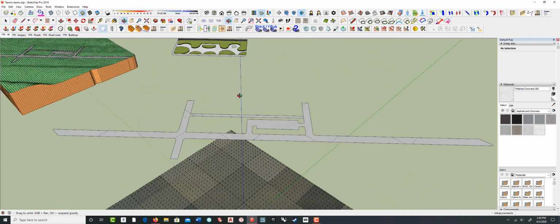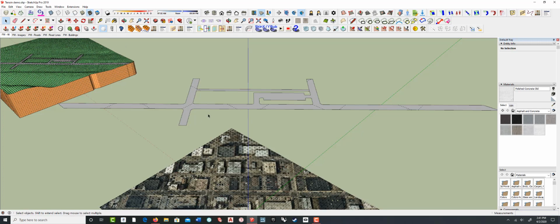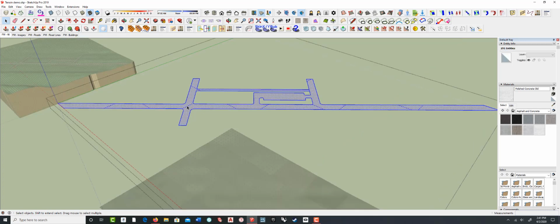And you can see here, I trace this. There's actually a 2-dimensional version of this that they provide with the high-res imagery, but I use that to trace over the outlines. It's one of the things that's really nice about it. It's great to use, but even with it as a group, these lines end up getting connected to everything. Now I can open this up and delete these out.